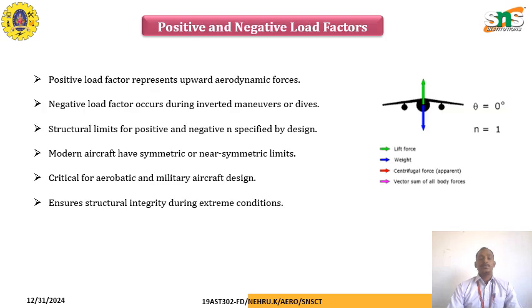Next, the positive and negative load factor. Positive load factor represents the upward aerodynamic forces, whereas negative load factor occurs during inverted maneuvers, spin, or diving conditions. The structural limits of the positive and negative load factor are specified by design for individual aircraft.